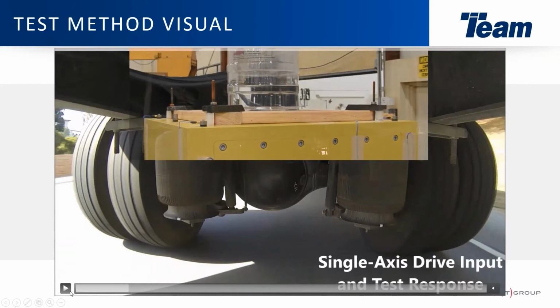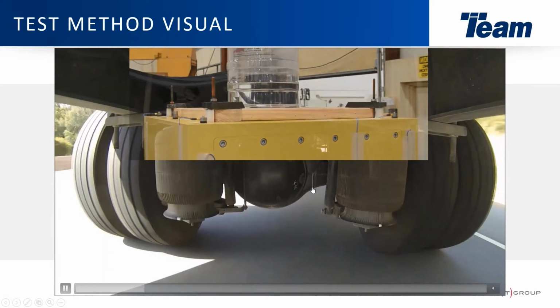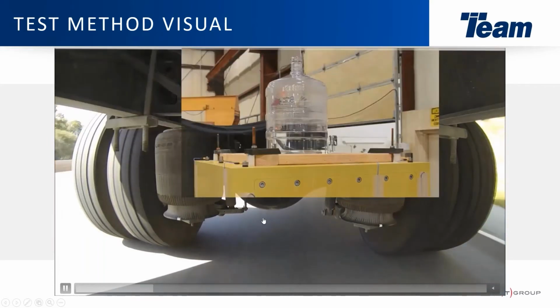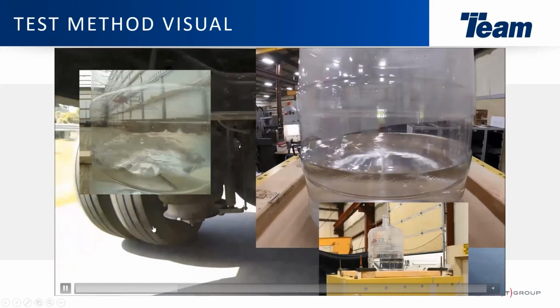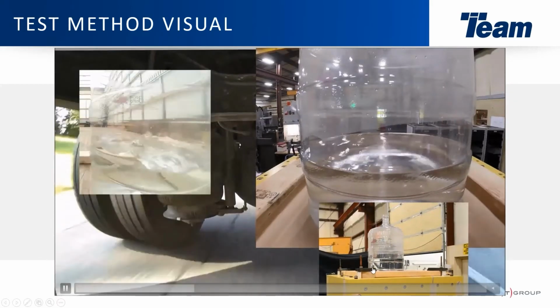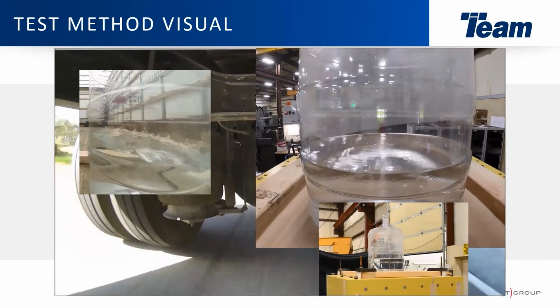So here you can see the input from the road is bouncing around, and replicating this water jug on the same test setup in the lab on a 6 degree of freedom system, this is the Cube 6 degree of freedom system here. We're actually constraining out the pitch, roll, yaw, and 2 horizontal axes in order to provide pure vertical motion.